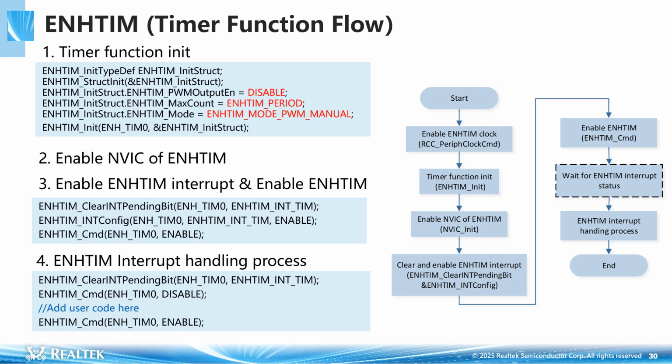When the counter value counts down to 0, it will trigger the interrupt. In interrupt handling, first, clear the interrupt flag. Second, add user-defined code.